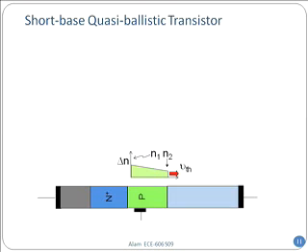Now I'll explain in a second why I didn't talk about it before, but let me first get you an expression for it. So now, instead of the current being simply N1 divided by W_B and the other side being equal to 0, because I have finite velocity on the collector side, I will have this V thermal multiplied by N2, because that is the velocity at which electrons can escape, and it cannot go any faster.